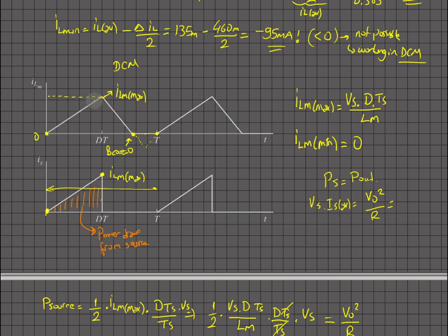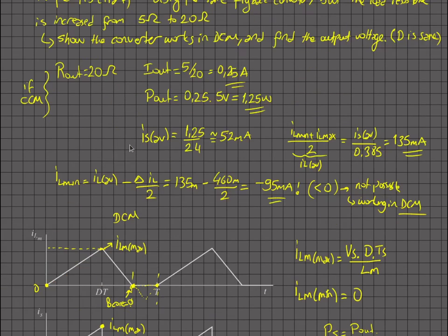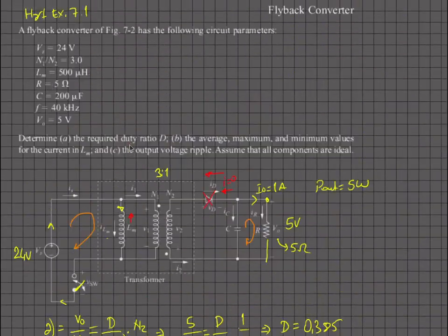The good thing is that once you have zero current here, all the transformer current will be zero. So you can have reduced core losses, or at least the period has reduced. That is a good thing.